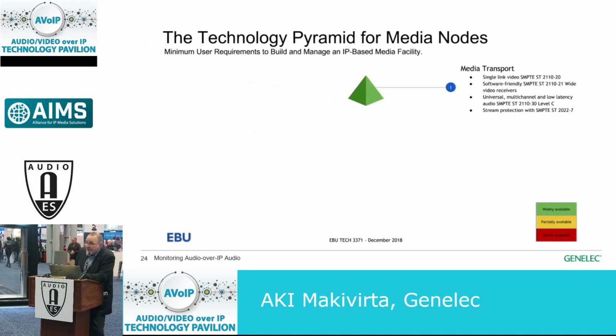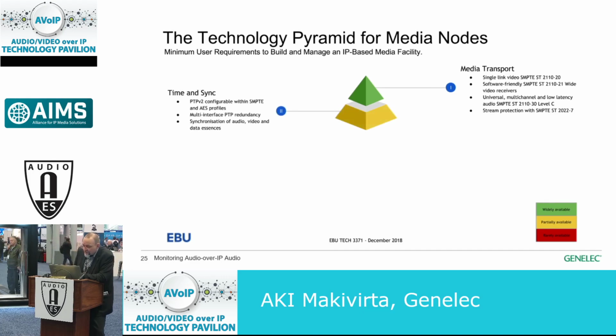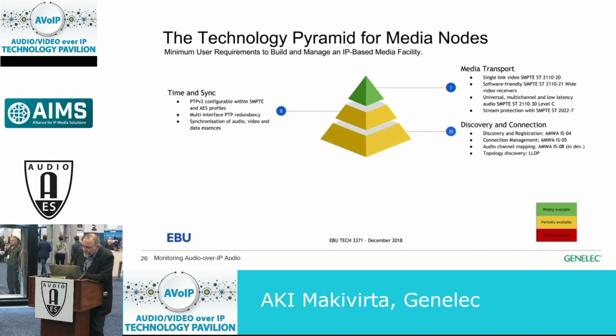One of the key aspects that the EBU, for example, is advocating at the moment is this concept of the technology pyramid that the previous presentation also quickly showed. At the top they have the media transport service, but they are also trying to make the point that you need some other very important layers in order to make the whole audio over IP, video over IP, media over IP networking work in a reliable fashion. The other layers that they advertise are the time and sync related aspects, and there of course PTP version 2 is central at the moment.